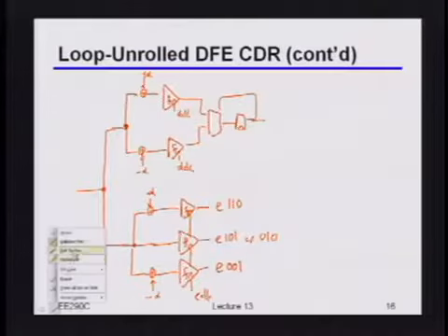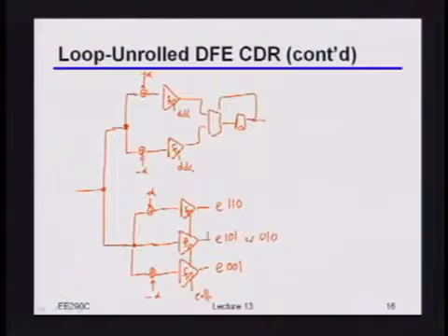Now, by the way, I should mention, this is kind of like building a fractionally spaced equalizer, in the sense that you're canceling the ISI on the edge position. But it's another way of looking at things, in the sense that you're really only doing it for this one unrolled tap, and you're trying to be clever about when you use which estimate, okay?